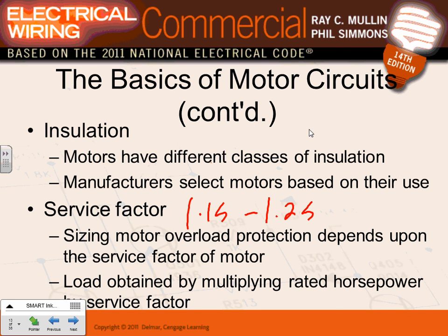So a service factor of 1, 100 horsepower is 100 horsepower. Service factor of 1.15, 100 horsepower can actually deliver 115. Who cares? When you size the overload, your size of overload can be bigger to accommodate for the increase of load in that particular motor.